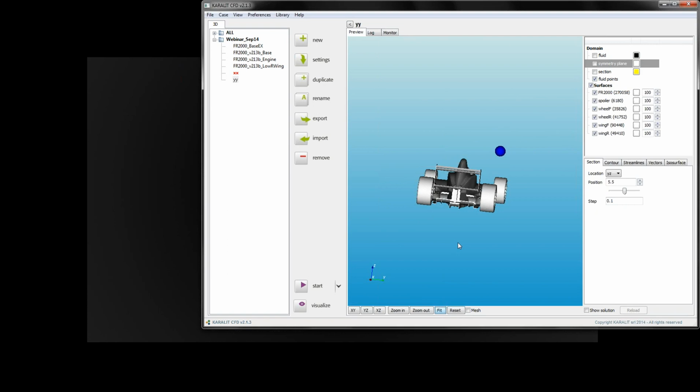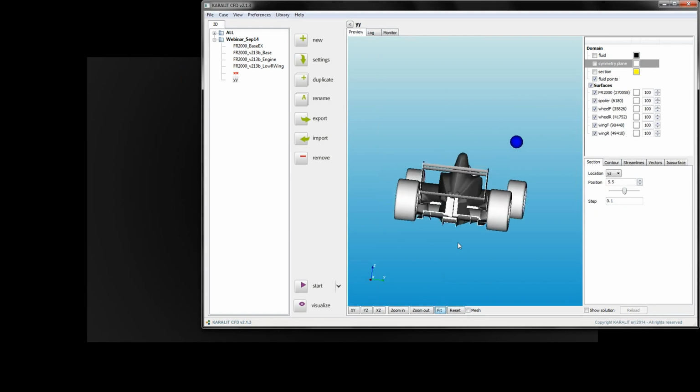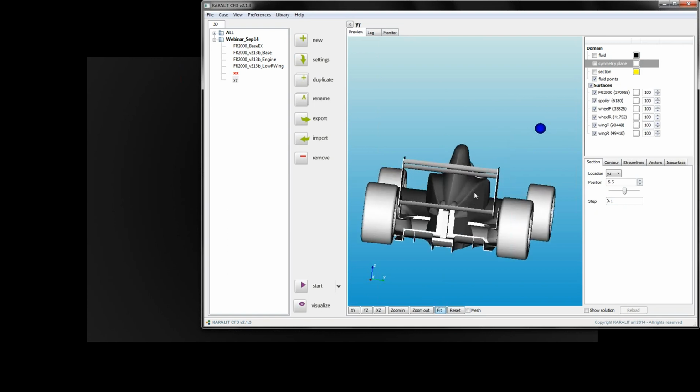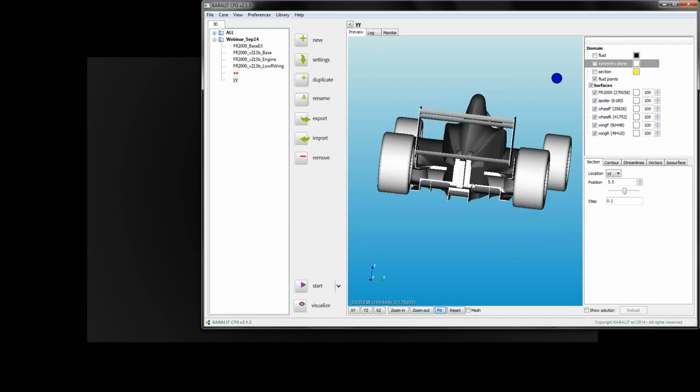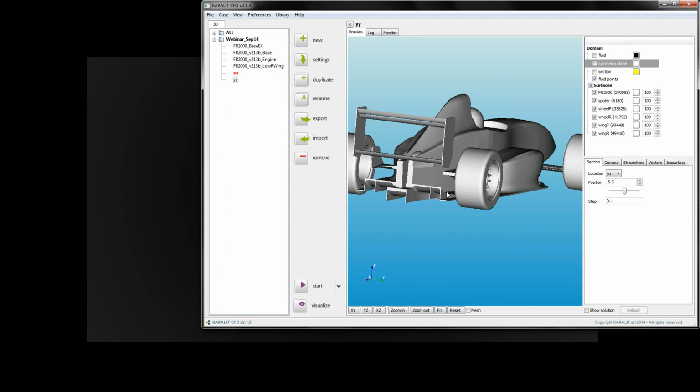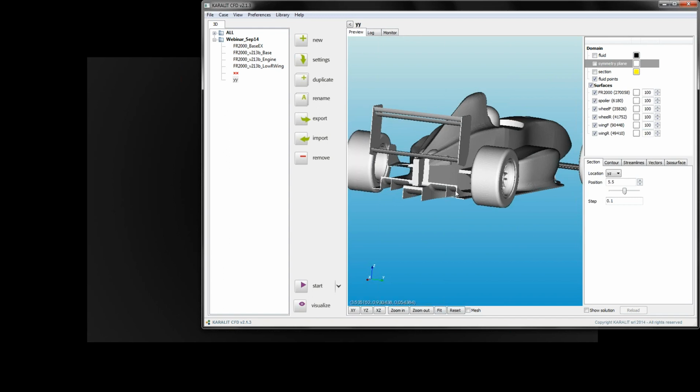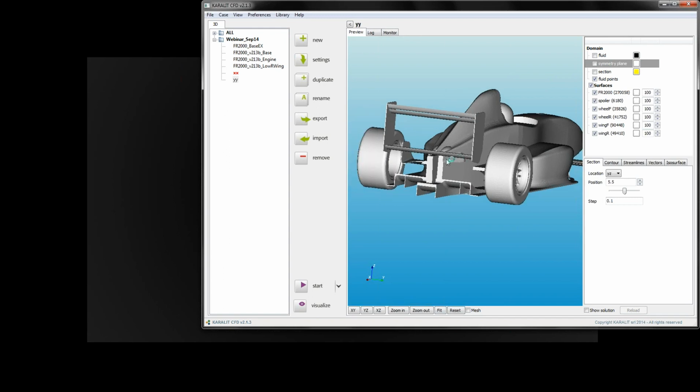back wing. This case is interesting because it's not actually trivial. It's a trivial movement, but it's certainly not trivial in terms of CFD, because what one is ending up with is surface meshes that are going to actually intrude with one another. It's a protruding case of geometry.